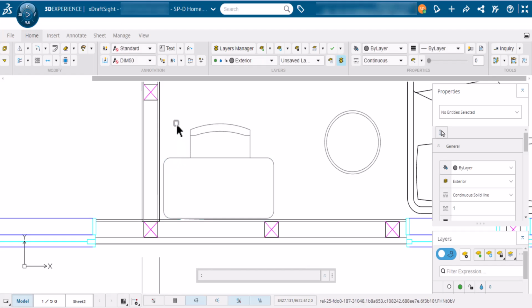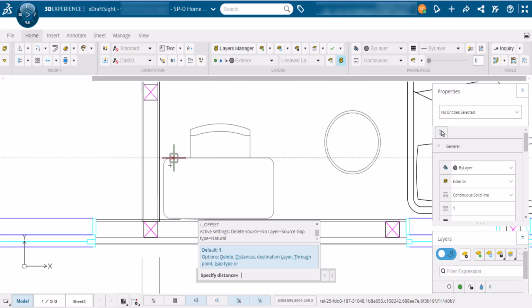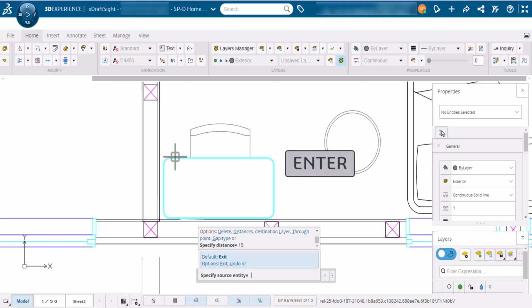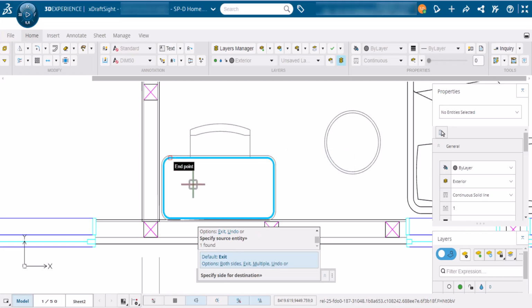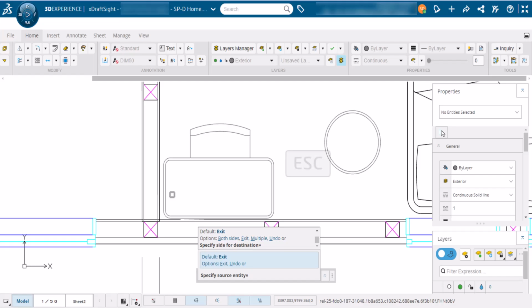We click on the rectangle, this automatically adds fillets to all corners of the polyline and ends the command. We want to indicate a bevel edge on the table, but do not want to draw another rectangle and fillet it. We can use the Offset command to create an offset copy. We will activate the command, enter a distance of 15 and press Enter. We then select the filleted rectangle, moving our mouse outside the rectangle adds a larger copy and internally a smaller copy. We want an internal copy, so we click inside the table to create it and press Escape to end the command.